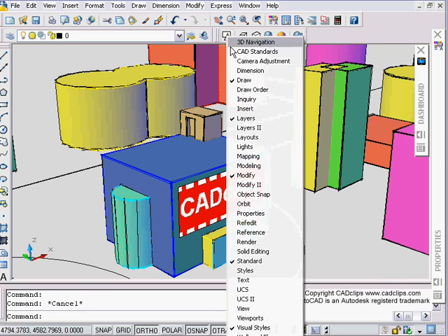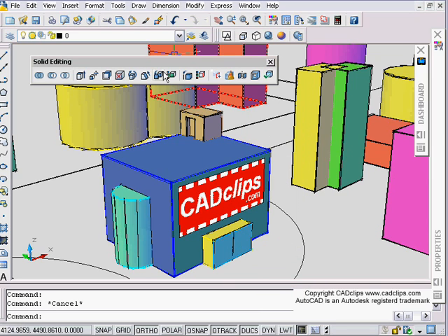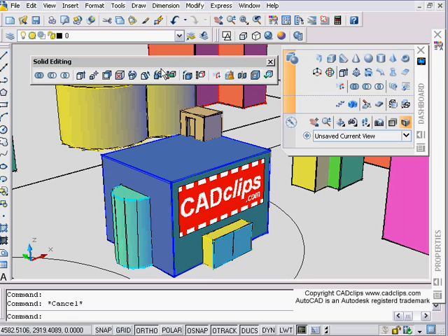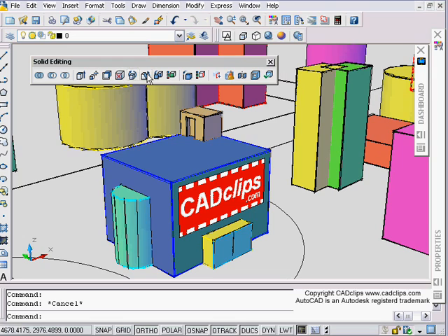So what I'm going to do is right click on here and go to my solid editing toolbar to start with, and right in here there's a copy face, and there's a bunch of other ones that I cover in some of my other videos that I encourage you to have a look at, and then we might cover some more as time goes on. And this is outside of our dashboard because some of this is redundant and some of it is, you can see there is some similarities over here, and then there's also some new ones. So copy face is only on here.